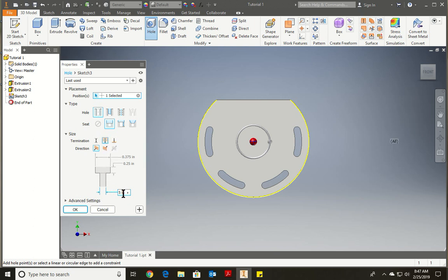And then we're going to change our thickness over here to 0.315. And we should be able to change this one as well. If I just click on it, it's showing us it's going to be 0.393. Click on this one, it should be 0.078. Perfect. And if you want to see the thread, we go to advanced features. No, where's the last one? The last one should have been to show the hole. I think it's right here, simple hole. There we go. We did the simple hole option. That was the first one. If I want to show the thread, it's going to show the thread here and so forth. We'll use a simple hole.